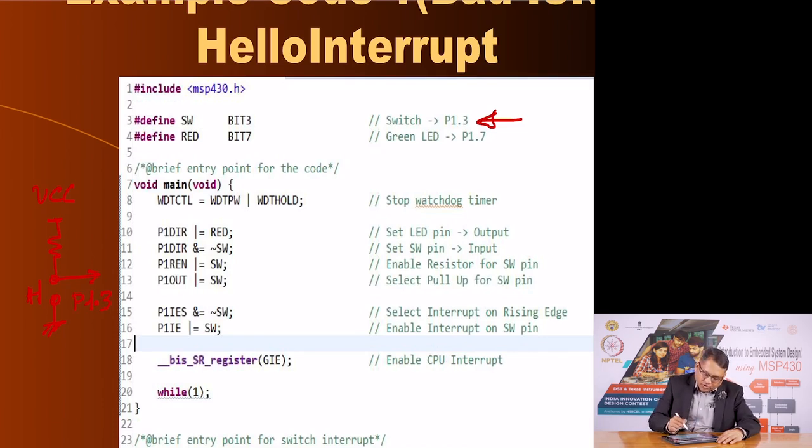And we also know that we have a LED connected on P1.7. So, we are going to use the available resources on the lunchbox itself to illustrate this idea of an interrupt and how an event on the interrupt, or interrupt being generated by the switch, can be handled with the interrupt subroutine. So, we have to include, as you know, this header file in our C program.